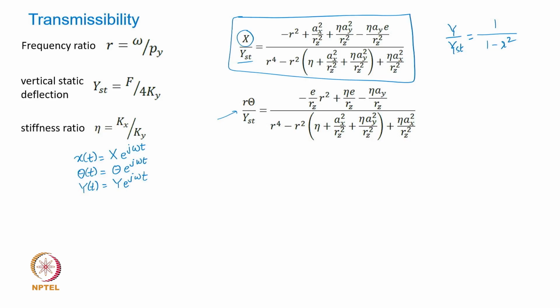And that's it. So can you tell me how do I get the resonance frequencies? The resonance frequency in the vertical direction, we know that omega resonance would be what? Square root of 4 ky by m. So very simply, that is the natural frequency. The resonance frequency in the vertical direction, the omega y, will be this.